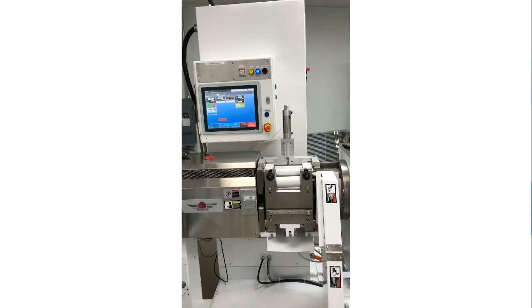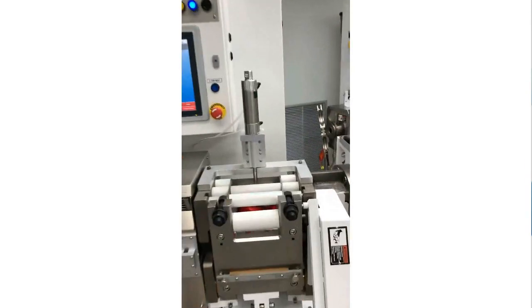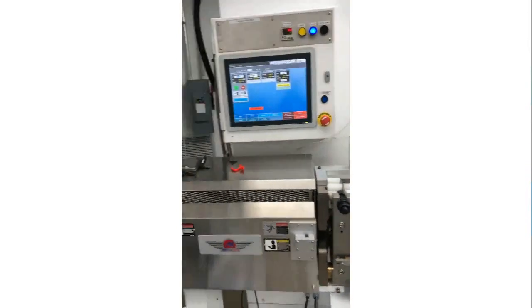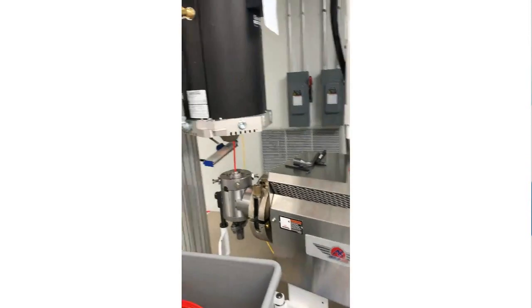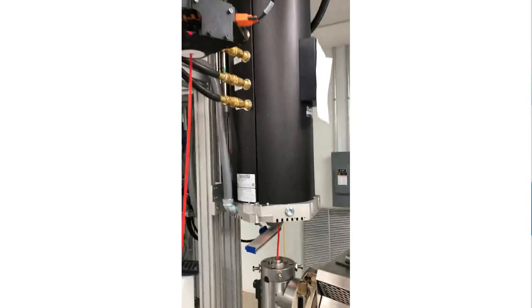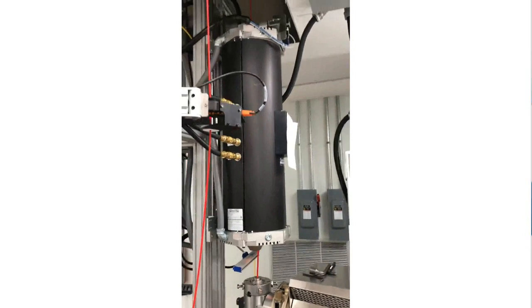In this video, the red material comes out of the extruder in a raw, uncured state, and it loops vertically upward to be cured. In this case, it's passing through an IR oven, or infrared oven, and through a laser micrometer for monitoring and measurement, and finally it's being coiled in a tote.